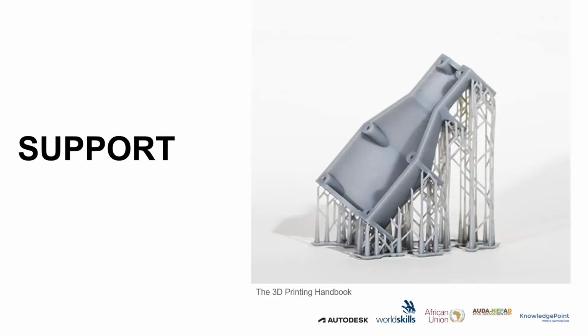So when you have a feature that doesn't have any material coming from underneath to support it, support is quite needed. If you look here, you find that in this particular direction you have an overhang. You will definitely need support. Without it, it will fail. So it's just for us to understand this.